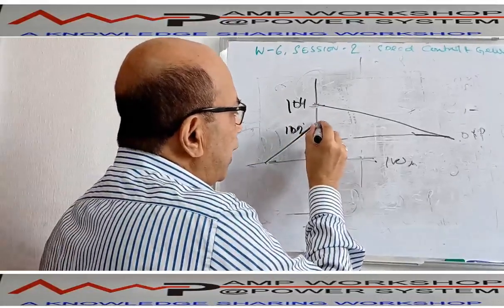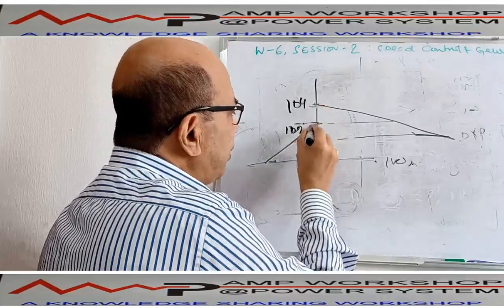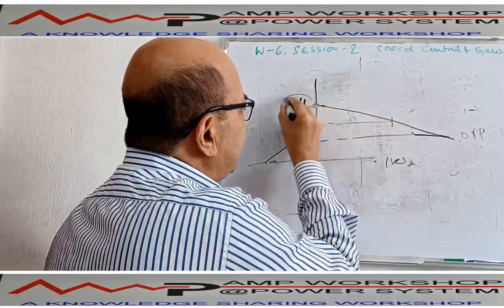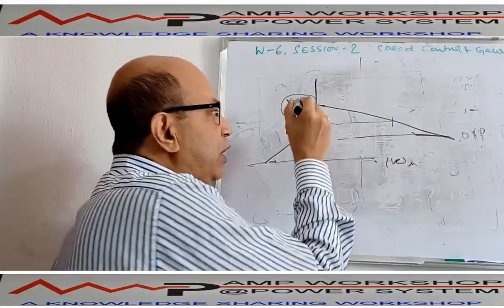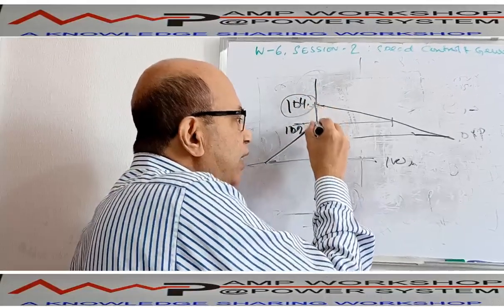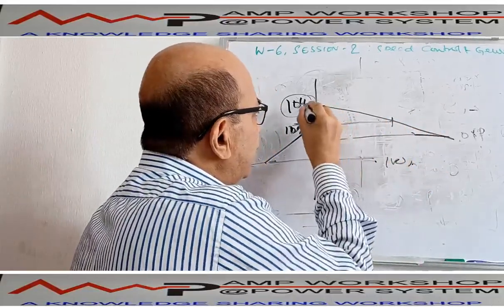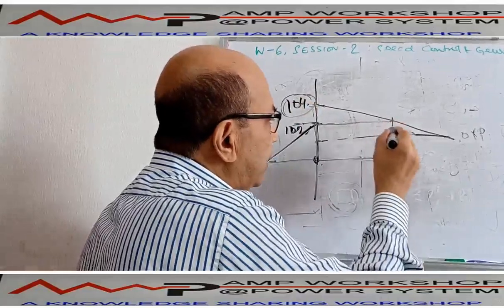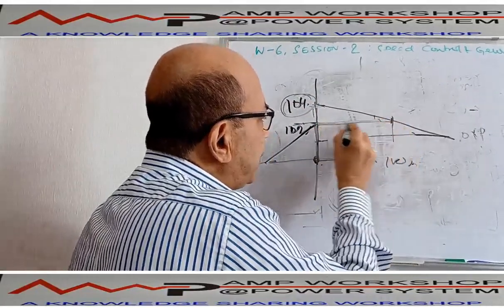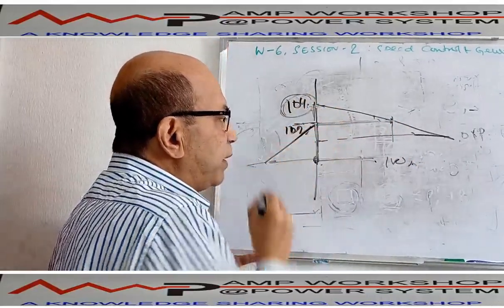So if you draw a line from here, what is happening? This machine is not taking any power, because all the power is coming to this machine, because this machine has a 104% Droop. Due to the loading, the machine speed will drop down. When the machine speed drops down to 102%, that means 50% of the machine is loaded. Suppose this is 50%, this is 50%. So when 50% loading of this machine has been done, the machine has dropped down from 104 to 102%.